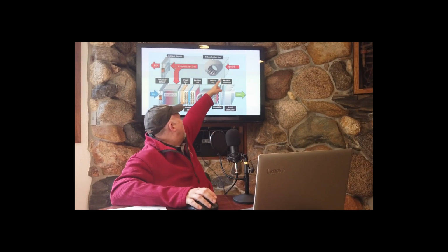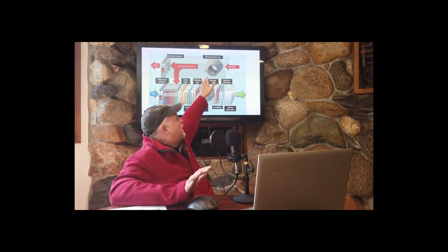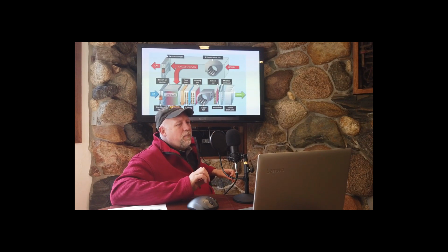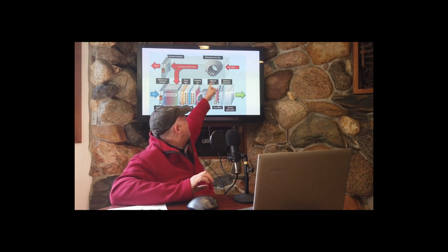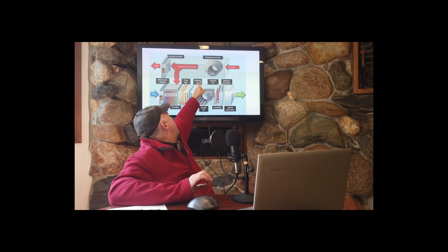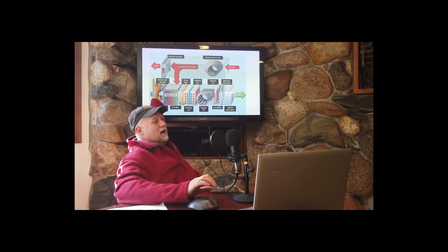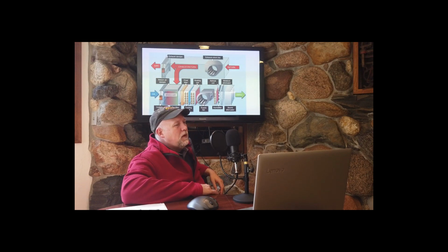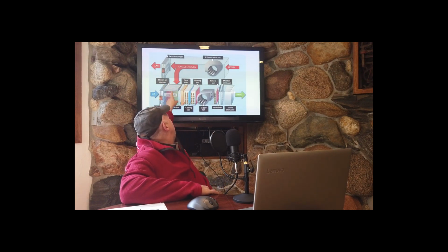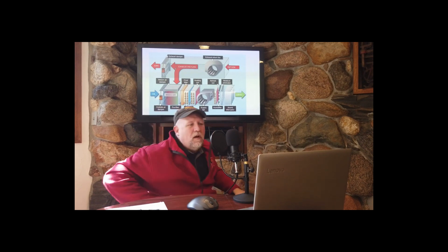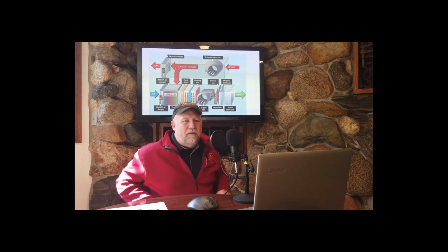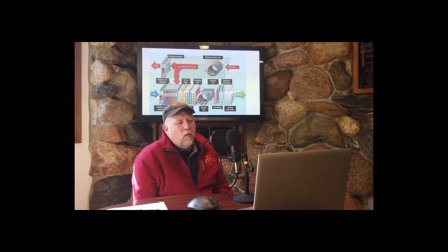So we've got the return air coming back through the exhaust and return air fan. It's called both because it pulls air into the air handler, that's the return air, and then it pushes it out these dampers for exhaust. Some of that air is exhausted, some of it is returned, mixed with outside air. There's our mixed air section. And now we go through a pre-filter and final filter. Like I said, if we have a really expensive final filter, we want something that's cheaper upstream of that.